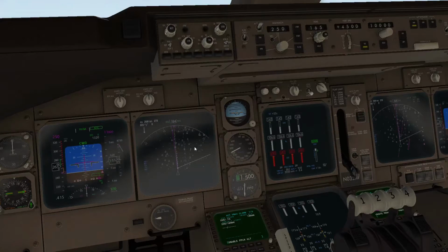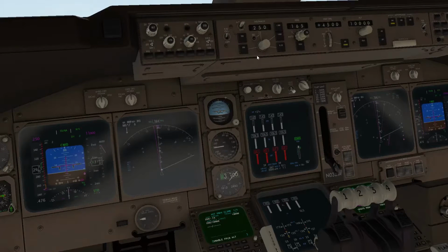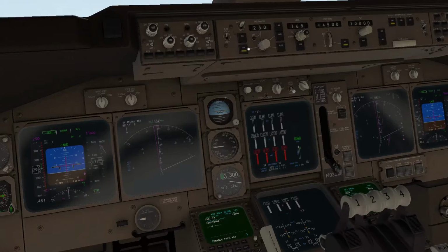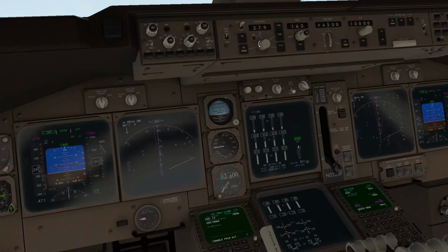So it will automatically set the vertical speed to the desired angle. And now we need to follow this flight path which is shown in the map, like this. So as soon as the plane will reach this point, we will be turning the plane. We'll also turn the speed limiters, and we will set the speed to 80 for the climb.